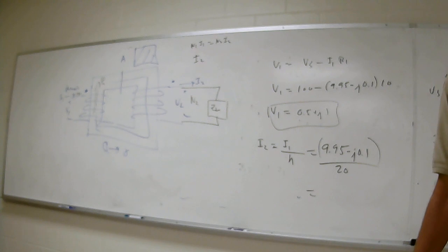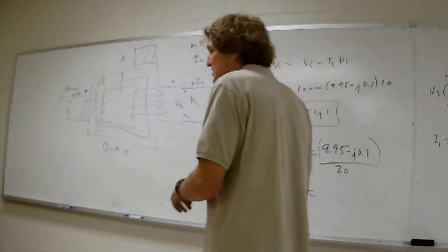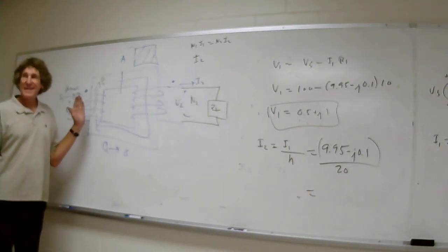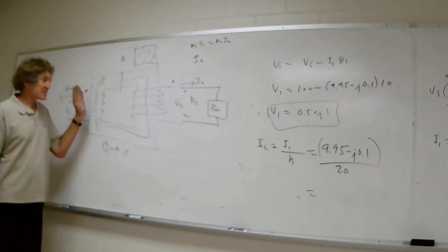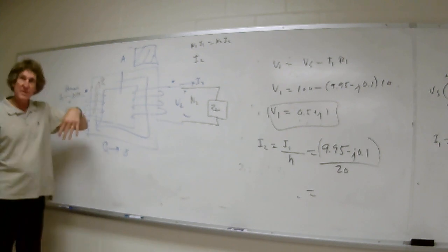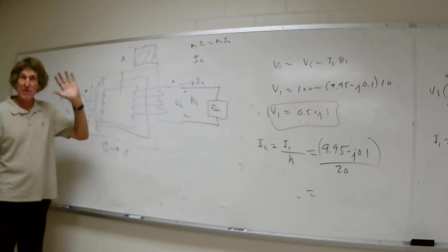By the way, that works 99.999% of the time for any low frequency transformers. Now, there are some tricks with transformers that you'll get into in power. One is hysteresis loss: in here, you've got magnetic dipoles, and as the current flips back and forth, the dipoles burn up energy, just like a lossy dielectric.